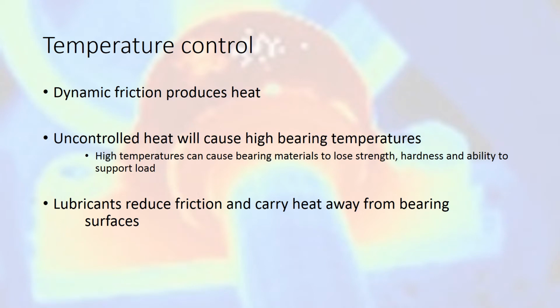Temperature control. The amount of force required to overcome friction will produce heat. If the amount of heat is uncontrolled, that can cause a high temperature condition inside bearings. And potentially that high temperature can cause some negative repercussions. It can cause your bearing materials to lose strength, hardness, and also the ability of the lubricant itself to support